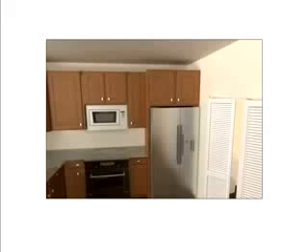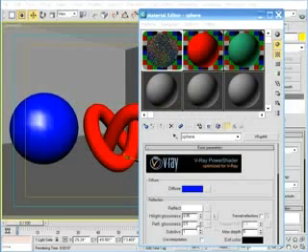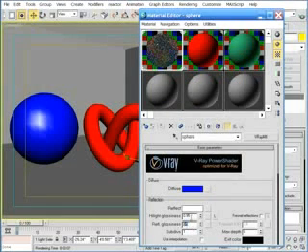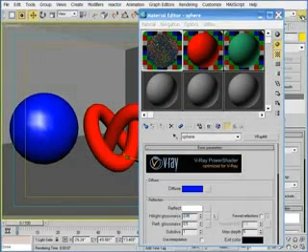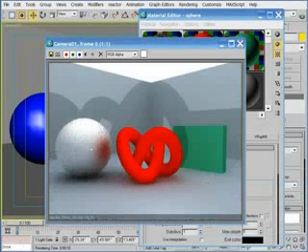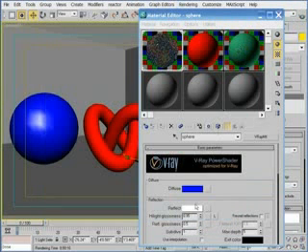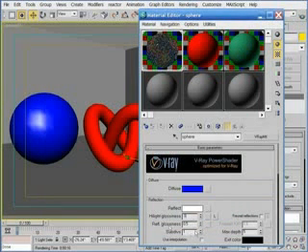While separating these values, you have to be careful not to go to extremes to the point that your materials are no longer believable. For example, if I place the reflection glossiness to 0.5 and place the highlight glossiness to 0.95, the result is clearly not realistic. Likewise, if I flip these two values, the result is equally unrealistic.